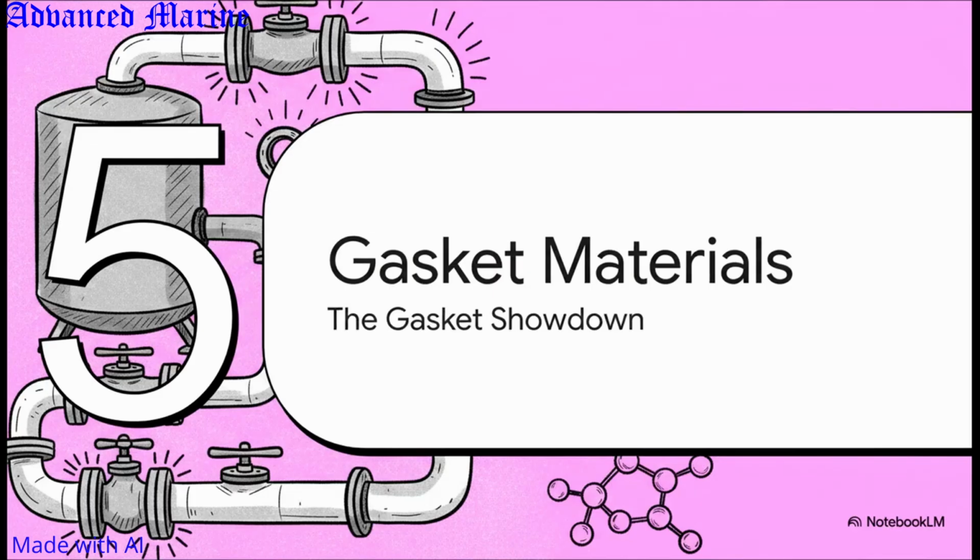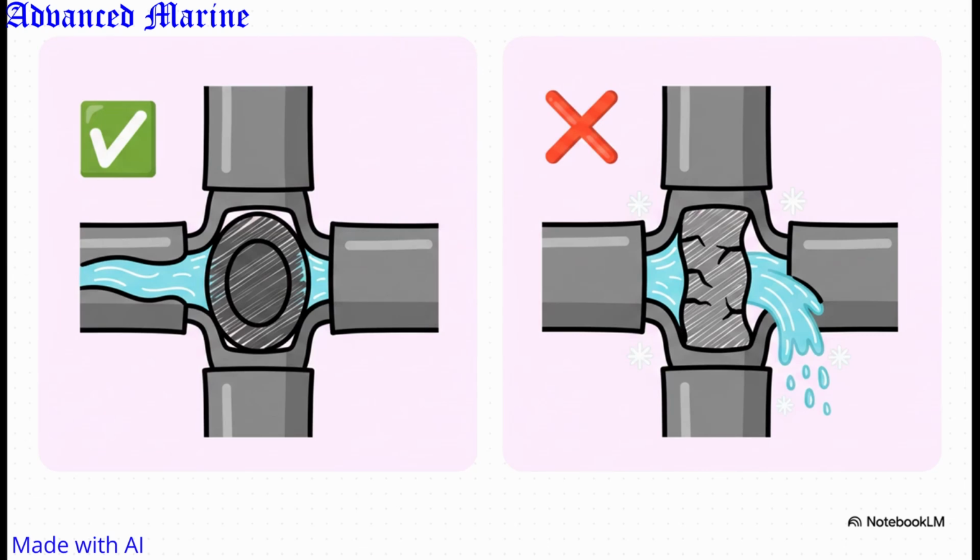Moving to Section 5, sealing tight, it's time for the gasket showdown. We've got the tanks, the pipes, and the valves, but wherever two pieces of metal meet, you naturally have a joint. To prevent our alkaline-reducing agent from escaping at these joints, we need highly specialized seals. When you're designing these systems, you'll find ammonia's compatibility with elastomers, the rubbery materials used for seals, varies wildly.